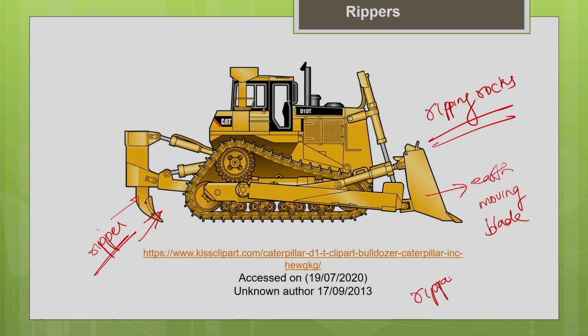You have to check the rippability of your rock. For that, there are some special methods like seismographic techniques. We are not going to discuss that in this particular lecture. Based upon that, you can check whether the rock is rippable or not. Once you know that the rock is rippable, you can use this technique for ripping it. That will result in huge saving in the cost.